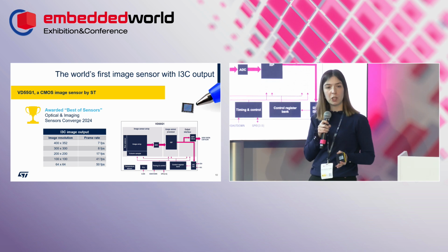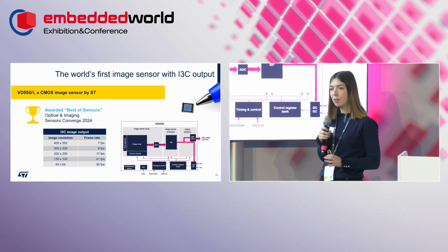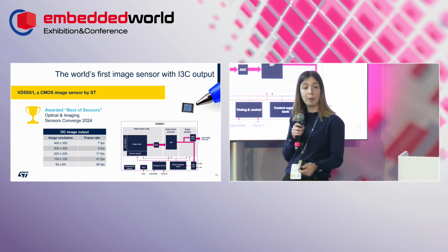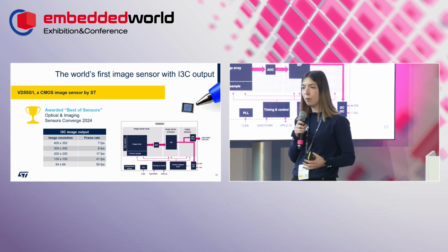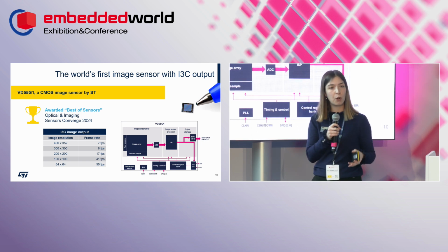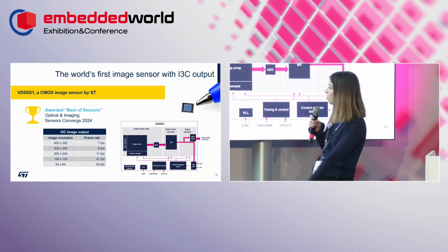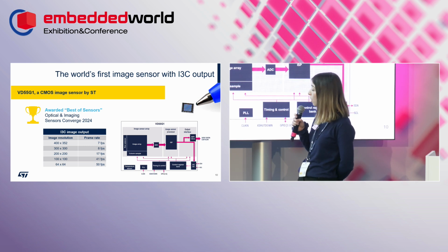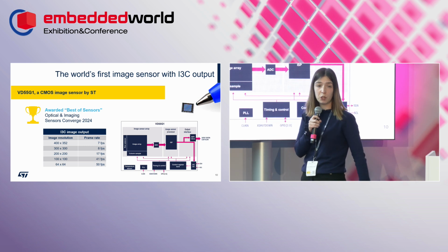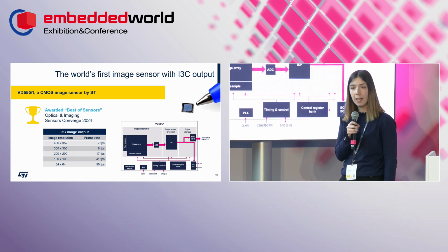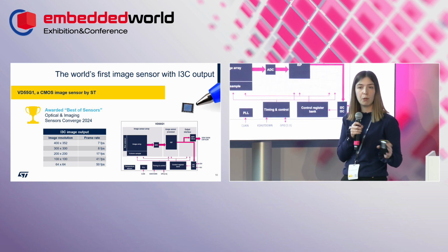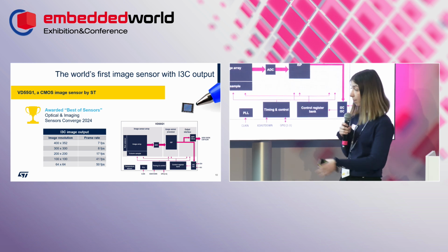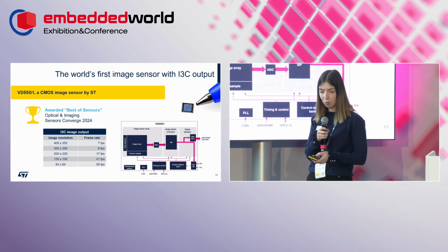But for most of the imaging applications, mainstream ones, if it's about reading the barcode on a coffee pod for a coffee machine, if it's about looking if there are no intruders around your vehicle, then the frame rate we can achieve with MIPI I3C is way enough to do simple applications. You see that you can reach a few dozen frames per second. And knowing that you can do AI character recognition from a resolution of 128 by 128, typically, it's perfectly suited for those types of applications.